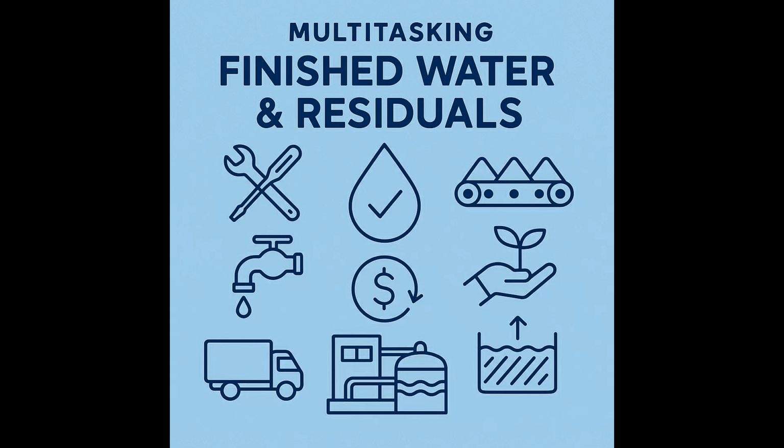What about storage for land application? Storage and handling choices impact cost and labor significantly. Silos with automated conveyors offer the highest capital cost but generally lowest labor, best odor control, and buffer capacity. Using roll-off containers or designated floor bins is lower capital, but usually means higher labor for loading, moving bins, and more exposure to weather. Lagoons are sometimes used for liquid sludge storage prior to dewatering for land application, very low capital but high footprint, potential odors, and labor-intensive cleanouts. These choices directly affect staffing needs.